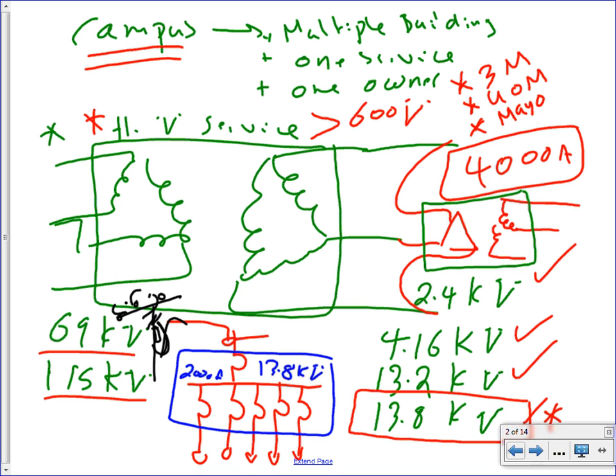I don't know if you can see. This wire, at a certain point right here, comes down all the way and goes to the building. So somewhere here there will be the demarcation point, right at the pole that's bringing the power to your building. It depends on where they want to put the demarcation point. Typically there will be a fuse disconnect on the pole. The secondary side of the disconnect will be your demarcation point. That's where you bring your cable up to the pole, and Excel will tie it to their switch on the pole. That's one way of doing it.